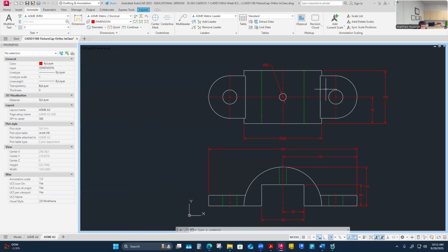Let me just think of the overall ear size and not worry about the hole yet, but just the size and location of this. So the size, well, it's got some radius. I need to call out a radius feature of it. That's definitely one component of its size. So I might even pull up the radius.